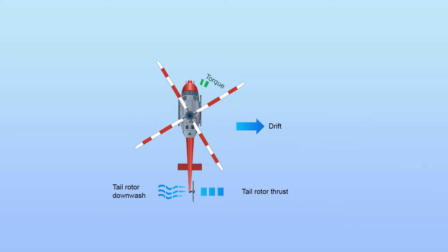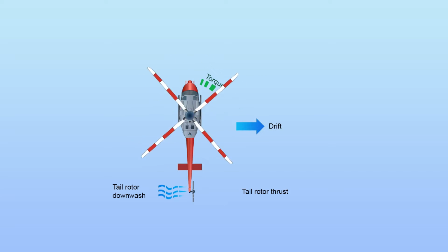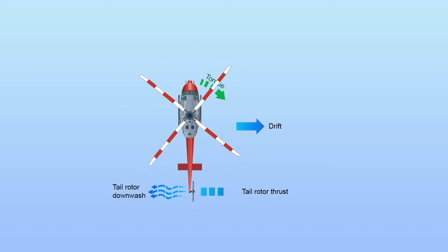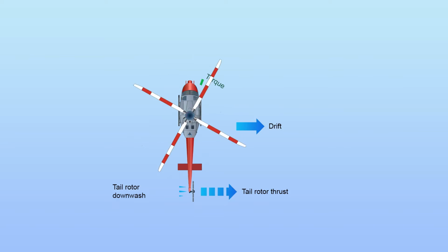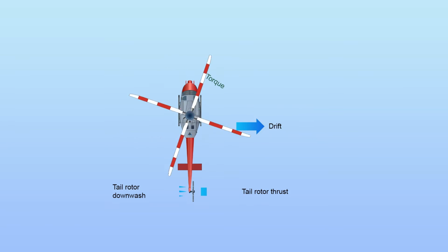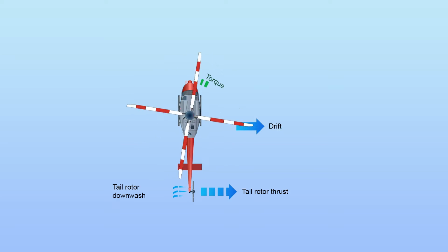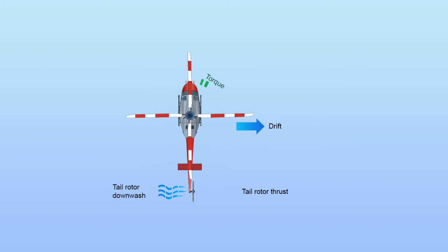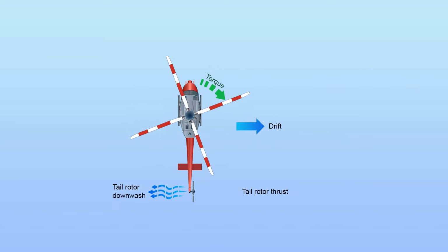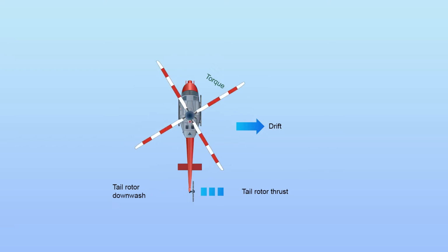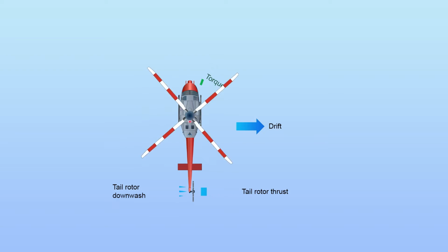If the transmission is mounted so that the rotor shaft is vertical with respect to the fuselage, the helicopter hangs left skid low in the hover. The opposite is true for rotor systems turning clockwise when viewed from above. In forward flight, the tail rotor continues to push to the right, and the helicopter makes a small angle with the wind, and the rotors are level and the slip ball is in the middle. This is called inherent sideslip.